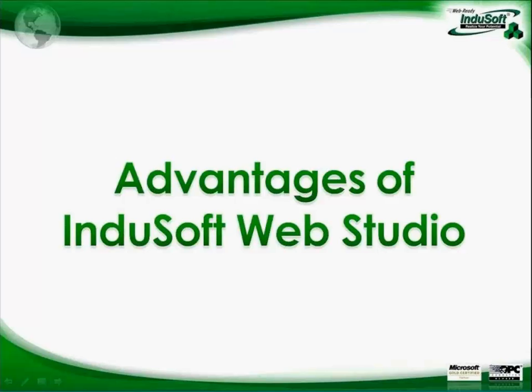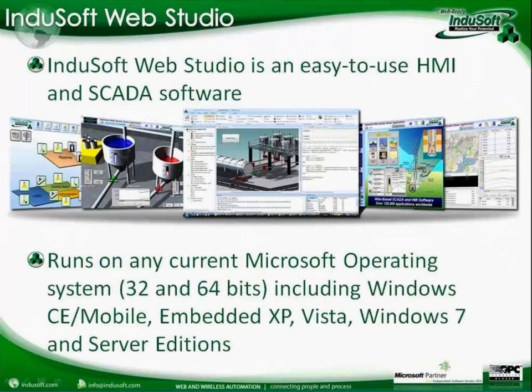So just an overview about the main and unique advantages of InduSoft Web Studio that are quite important for grain monitoring applications and farming automation applications in general. First of all is the fact that InduSoft Web Studio is a complete HMI SCADA package that integrates all the features you need to read data from the devices, to communicate with the controllers, save data to databases, to history files, SQL relational databases, create graphical screens to monitor online data, history data, provide a dashboard interface so you can read data from the history and provide some dashboards with meaningful information.